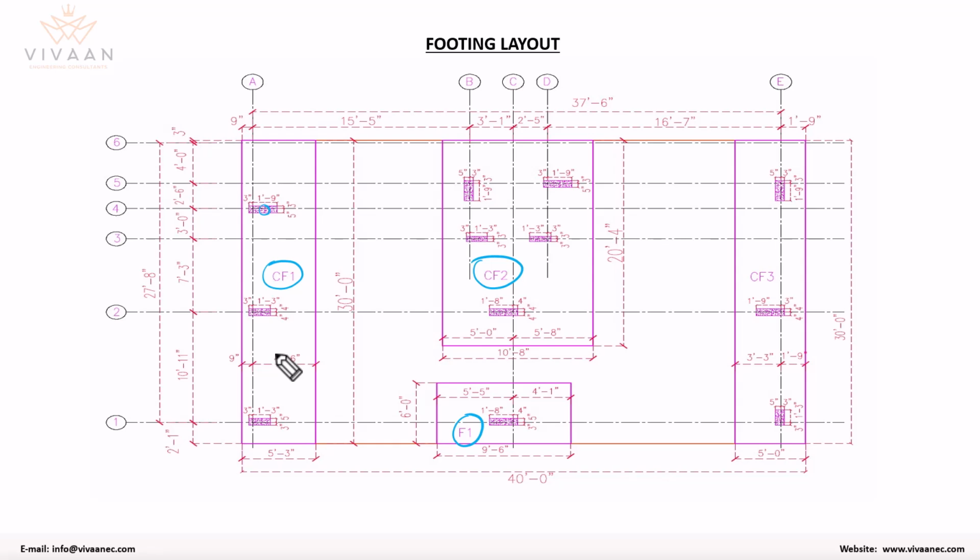Again, this is where people tend not to invest money. But if you think the soil is not hard, we need to send the soil samples to the geotechnical lab and check the soil strength. Sometimes when we have loose soils and a multi-story building being built, we may need to go for pile foundations as well.